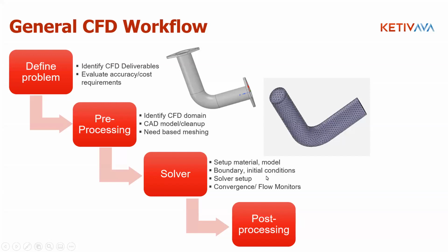With any fluid problem, you'll always have to define the boundary conditions, the initial conditions, and I guess that is true for structures as well, where you specify the load conditions before doing a simulation, right? And of course, you'll have to select the solver in terms of which discretization method you want to use in order to solve these equations numerically. Now, most of the commercial CFD software that is available nowadays has predefined settings to give you the best possible, most optimum solution. But in case you're more of a CFD expert and you want to play around with the solver settings yourself, you have the option to do that as well.